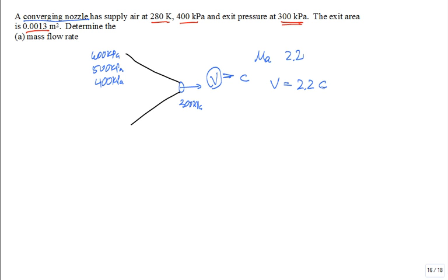So what you do to find that it's choked is, if the supply pressure is greater than the exit pressure divided by 0.528, it's choked. A lot of people just round that off. It's a half. So when the supply pressure is greater than 2 times the exit pressure, guess what? It's choked flow. Could I ever experience and hear choked flow, maybe in the thermal fluids lab?